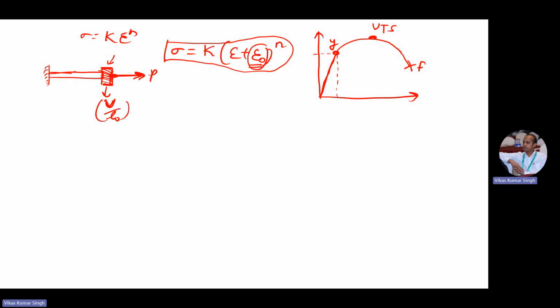What is the meaning of linear and non-linear? I'm trying to explain. So this line, this is stress and this is strain. So up to here, this line is linear, and there will be some slope, and that is constant, and this slope is nothing but E, Young modulus, slope of this line, that is constant. So in this formula, if we have to find out stress, we can apply this formula, stress equal to E into epsilon directly. So this is linear. Okay, how? Because this is in term of y equal to mx. m is the slope, x is the independent variable, and here x is in term of epsilon. Correct?